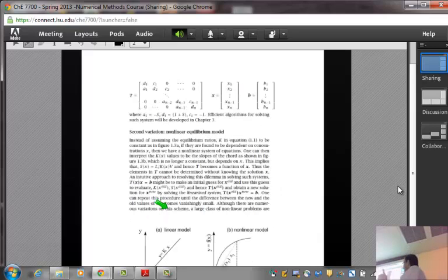Now, the same example, I've said, okay, now I have, instead of 3 tanks, I have n tanks. N could be any number. Often you will find in a plant, you'll have 50 stages, 100 stages. If you're separating very difficult material like uranium or material that have very close properties, okay, then you really need very large, like heavy water production from water. Okay, you'll need hundreds and hundreds of stages to do that separation.